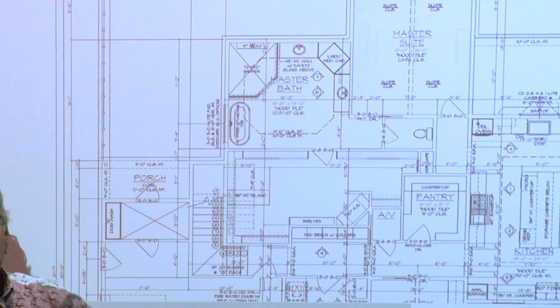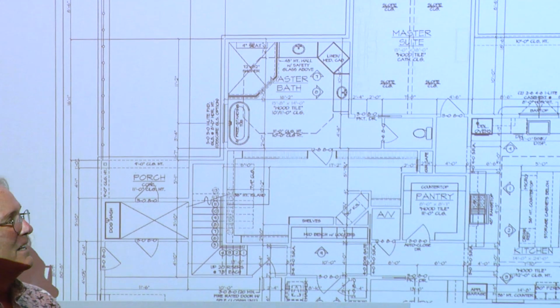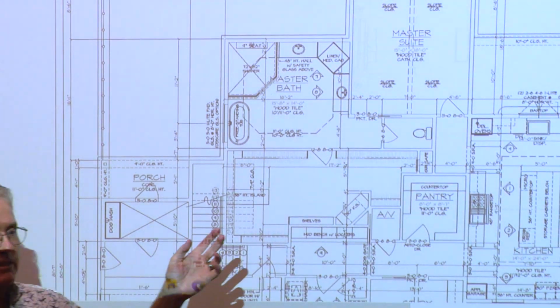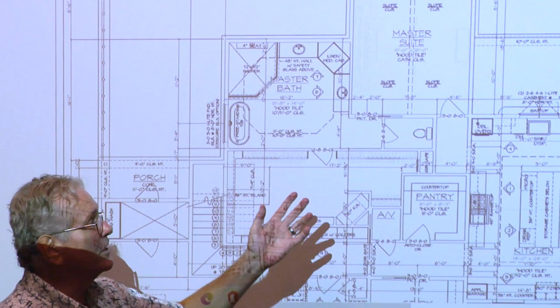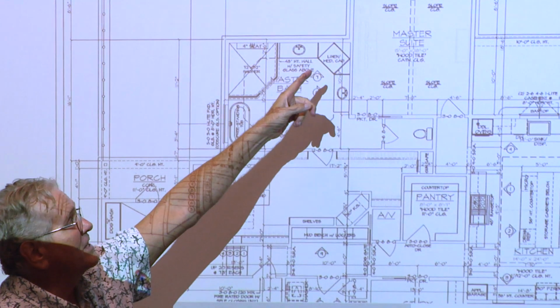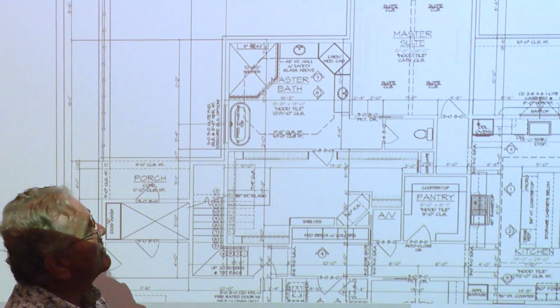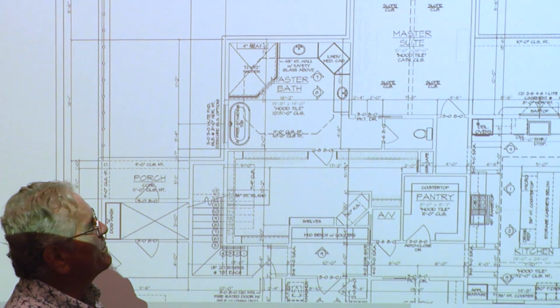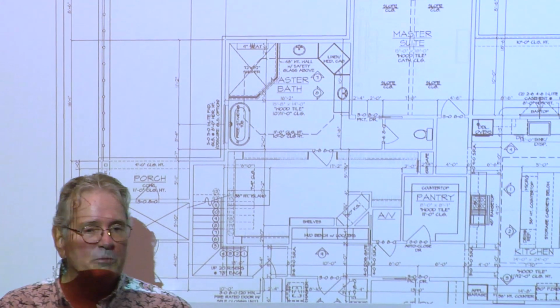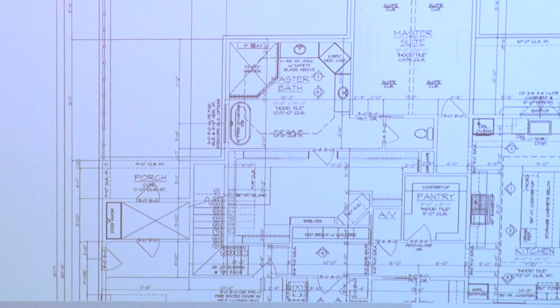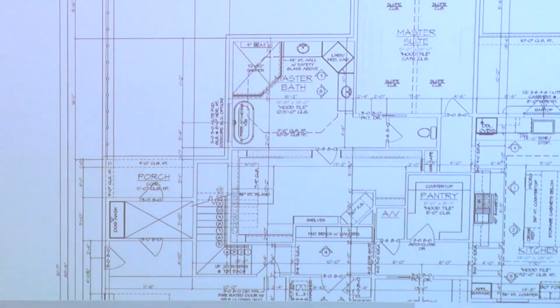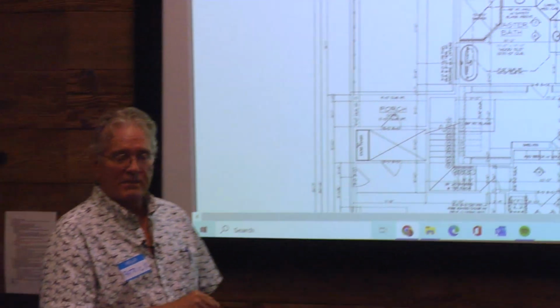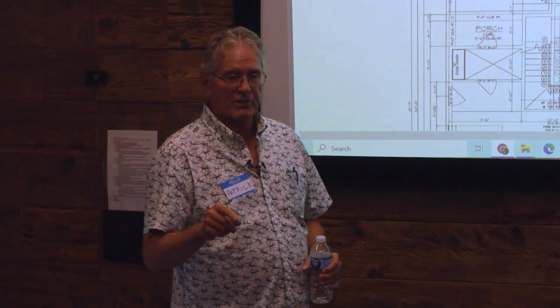That's kind of a test question, but that's how windows are shown. Of course, two-dimensionally, that's really all they can do. And they're called out, the size, 6050, I think that reads, or maybe it's 60. But that's the nomenclature for window sizes. Okay, it's 4 foot by 6 foot. And the width is always named first. It's always the width and then the height.